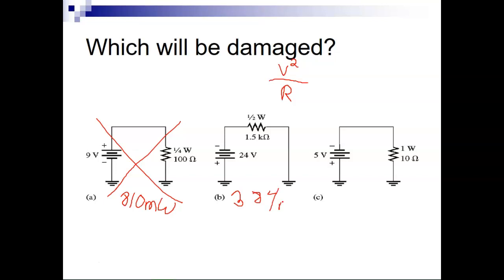384 milliwatts. We have a 1/2 watt resistor. Is that big enough? Don't think so. So 0.384. Oh yeah, it'll be enough. 0.5. Yeah, it'll be enough actually. That one's good.